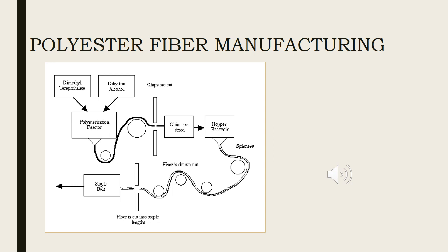The tow is then dried with hot air and then passed to a cutter for cutting to the desired length. These cut tow pieces are then wound on reels and transported to a warehouse where they are matured for a minimum of 8 to 10 days before dispatching to the spinning mill.